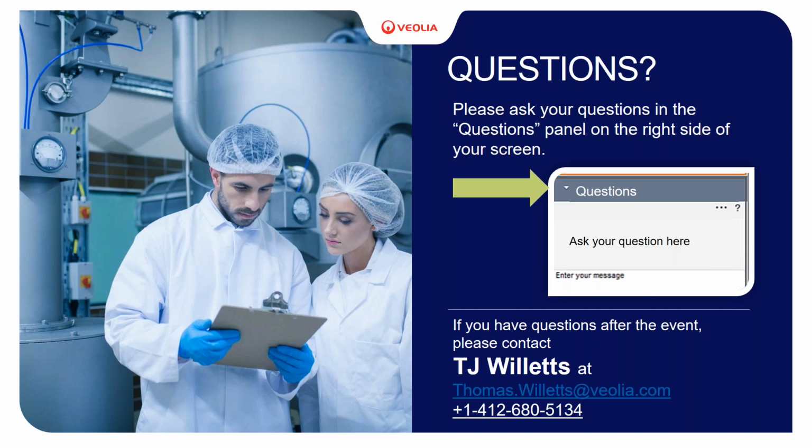Another question is, if the plant communicates a spill in chemicals or an unknown substance and it gets routed to a calamity tank, what is the best way to handle that influent wastewater in the calamity tank? Depends on what's in there. I hate to say that. If it's just high COD, if they've had a spill of a product, that can be bled back in.